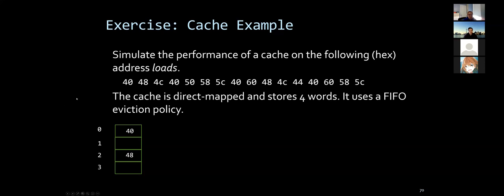It goes here because you truncate the first bytes, and then you look at the address left. You're going to have 8, so it means it's 8 bytes. So the first 4 bytes go here, the next 4 bytes go here, so everything starting from 48, from 8, needs to go to this block, right? And the next 4 starting from C, which is 12, goes to this block. Yes, 47 goes to 1, that's correct. So this is how the mapping works.